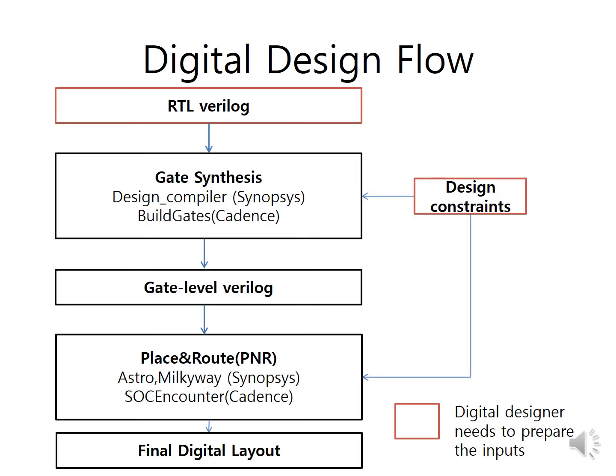This is a simple digital design flow. First, you provide RTL, register transfer level Verilog. You may provide behavioral code only if such behavioral code is synthesizable. So there are two distinctions there. You can write a function, but sometimes it cannot be implemented in real hardware. So you must understand what can be done and what can be implemented. Throughout this course, we will see that.